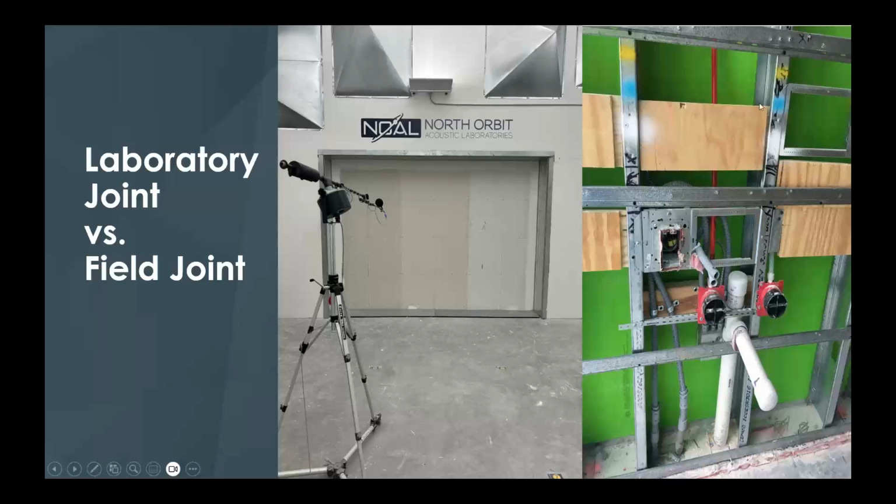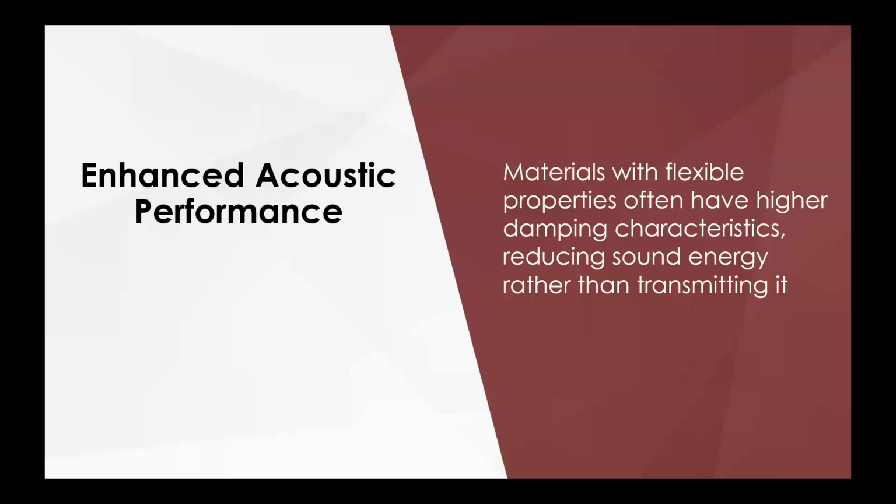This picture is kind of comical to me. A lot of you guys probably see what I'm looking at here. This is an RC. This is backing for cabinets. They're going to install the drywall through this, but then when they get the cabinet, they're going to install it into this backing. That's going to negate all your STC values you just gained by using an RC. This is a perfect photo to show what you bring up with management, with the AHJ, because that is not going to perform to that third-party sound report with all that stuff going on in there.